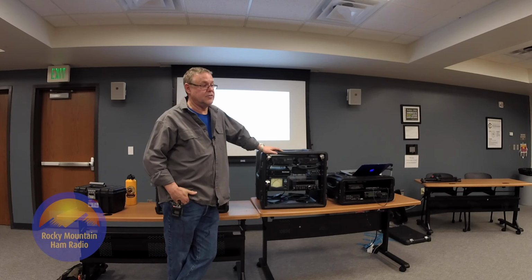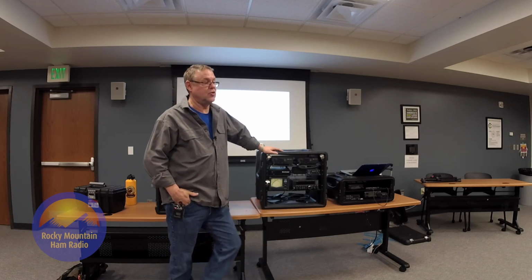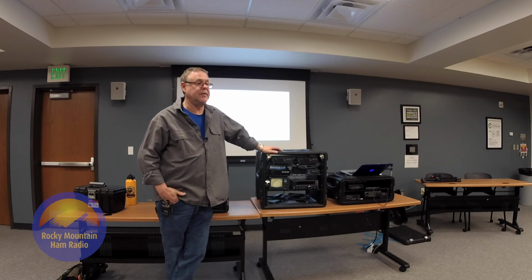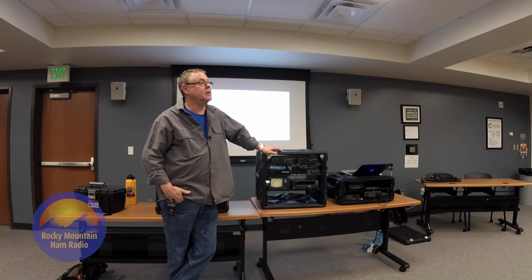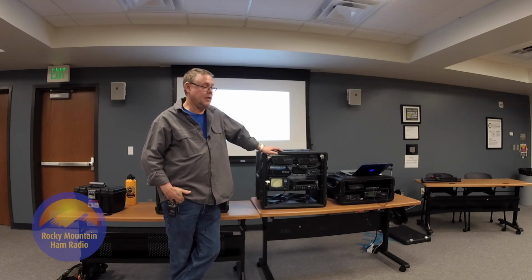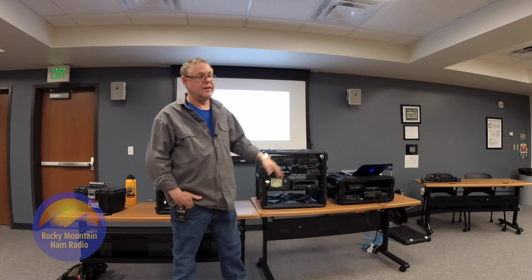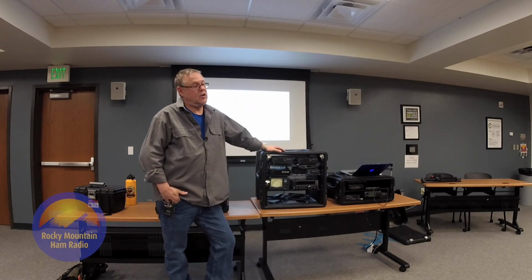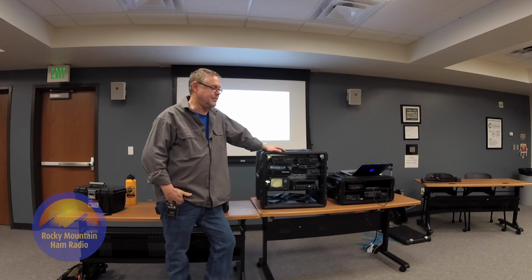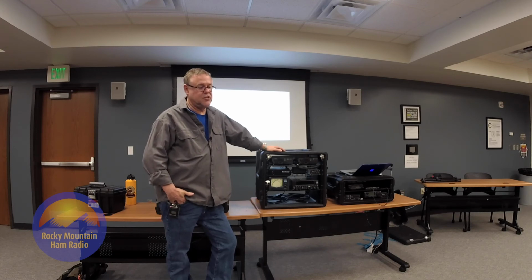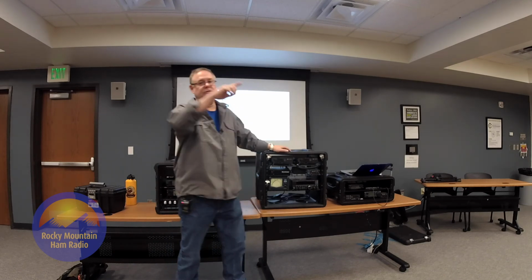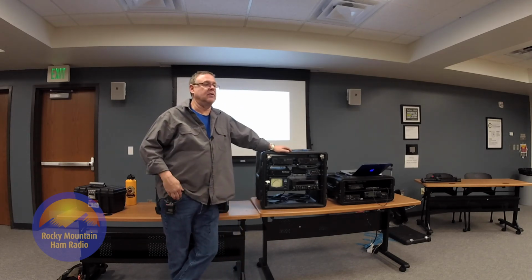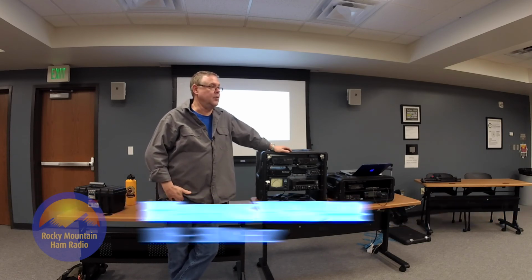But I carry an X50 with tripod. I also carry one of these dual band Cushcraft 2-meter 440 beams, 3-element and 4-element, that I can put up on the same tripod or the other tripod. Arrow, you can carry Arrow, but I carry a G5RV for HF that I can take if I need it. I also carry one of these multi-band dipoles, 80 through probably 6. My tuner tunes at the 6, but I forget who makes it, DX Engineering or whatever, that has the 12 gauge gray wire, and it looks like a fan dipole. I carry one of those.